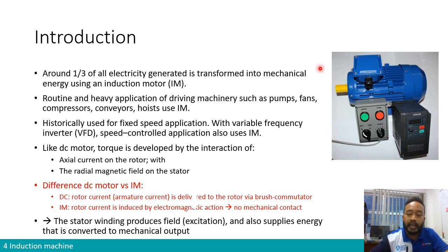It is basically the application of Faraday's and Lenz's law to induce a certain EMF, and therefore current, in the rotor structure. So in principle, there is no mechanical contact needed to deliver current. When I say no mechanical contact, it is for the purpose of delivering power to the rotor. So the stator winding produces the field excitation like in a DC machine, but in this case it also supplies energy that's converted to mechanical output.